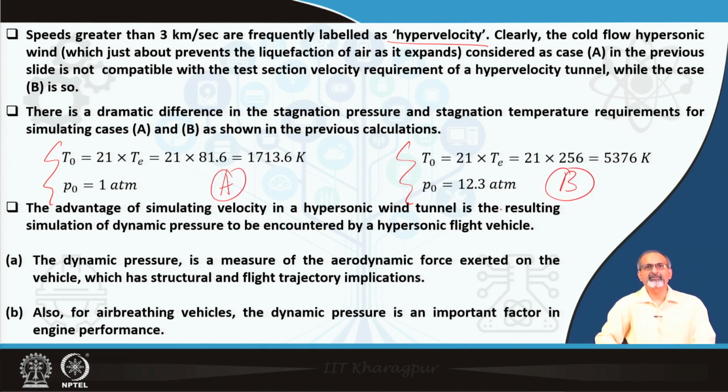The advantage of simulating velocity in a wind tunnel is the resulting simulation of the dynamic pressure to be encountered by a hypersonic flight vehicle. So, we are talking about simulating the appropriate velocity.